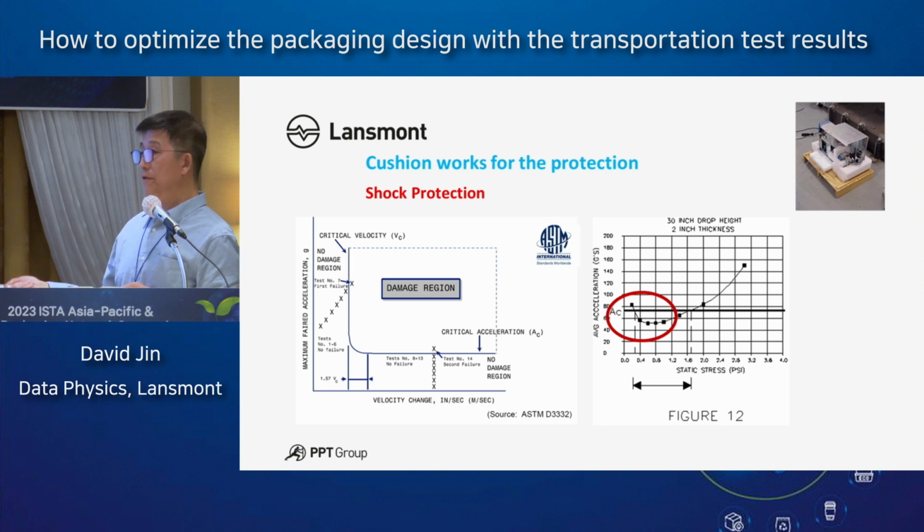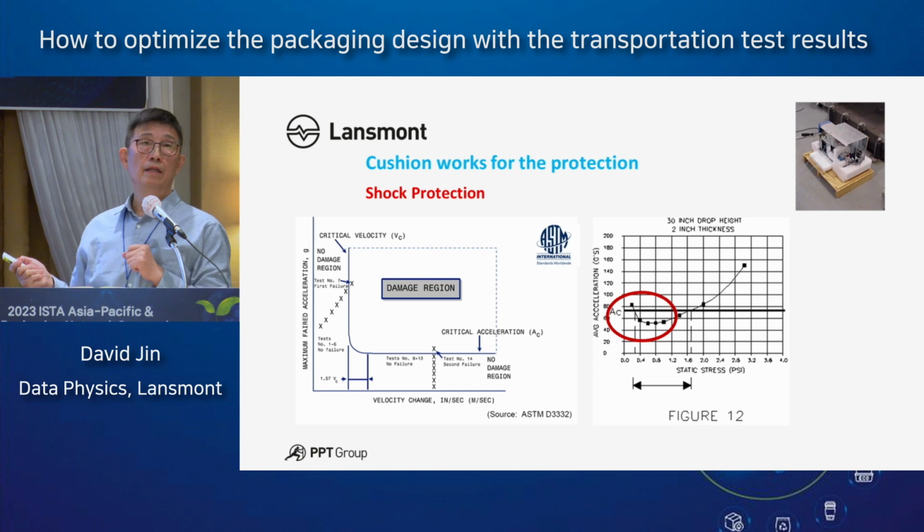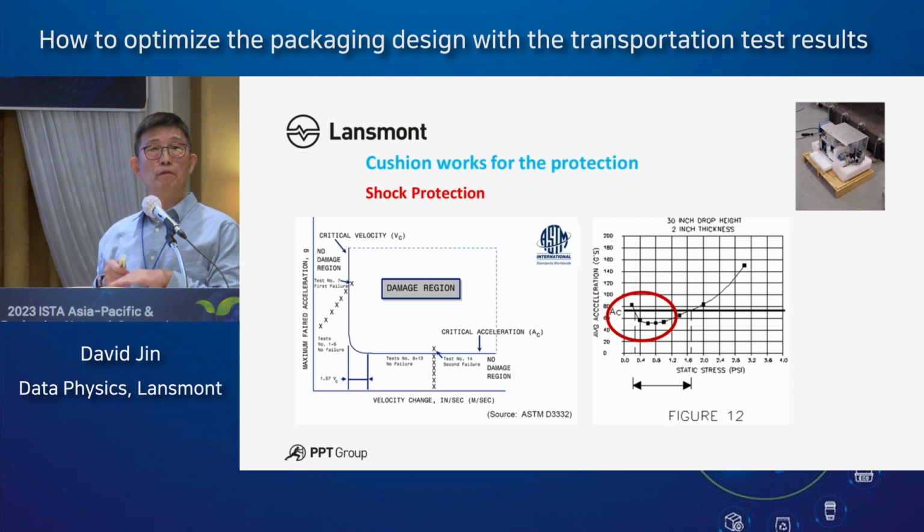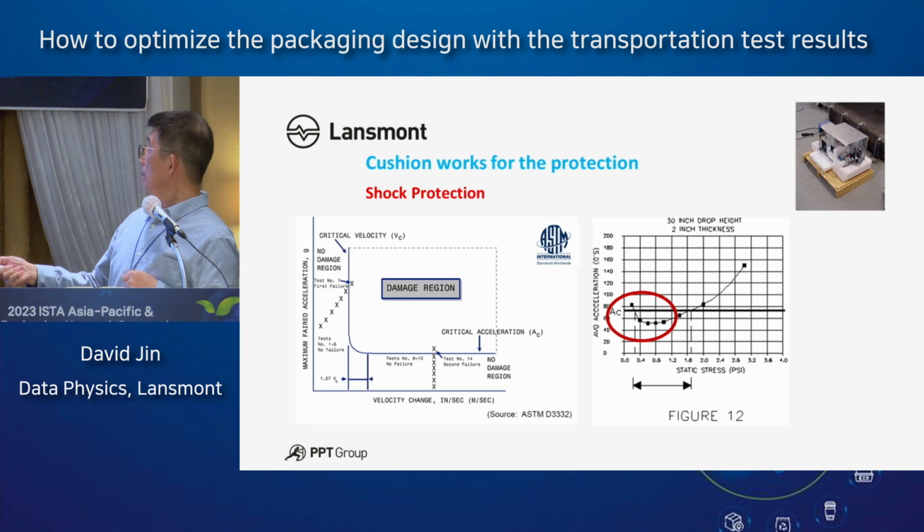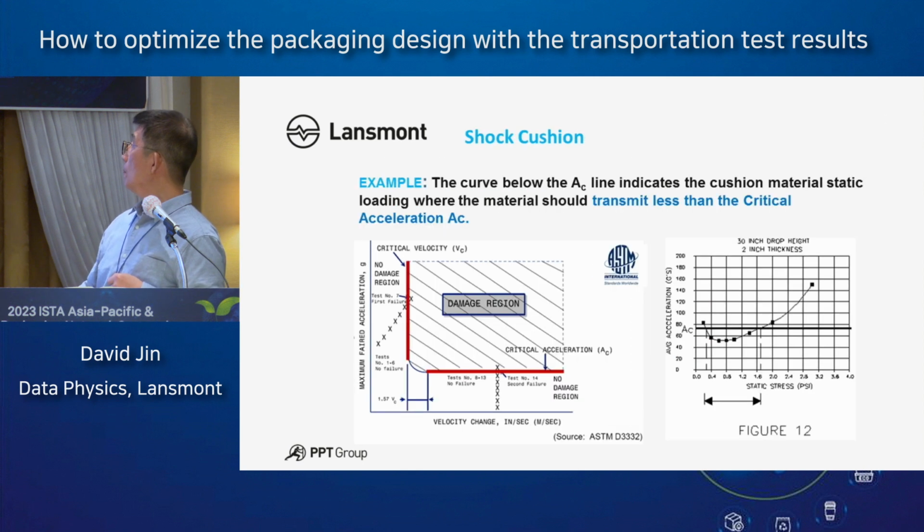then you find your product fragility standard. It has a corresponding acceleration level. If the product cannot bear anything over 50 G, please do that. So we have this AC here, it's the level, the ACs. That's the maximum acceleration we can achieve here.